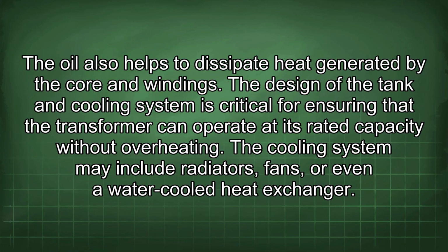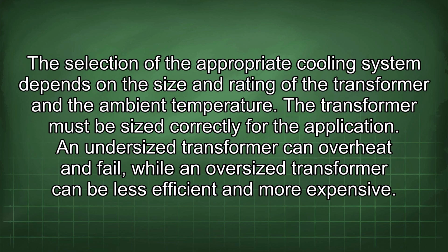The design of the tank and cooling system is critical for ensuring that the transformer can operate at its rated capacity without overheating. The cooling system may include radiators, fans, or even a water-cooled heat exchanger. The selection of the appropriate cooling system depends on the size and rating of the transformer and the ambient temperature.